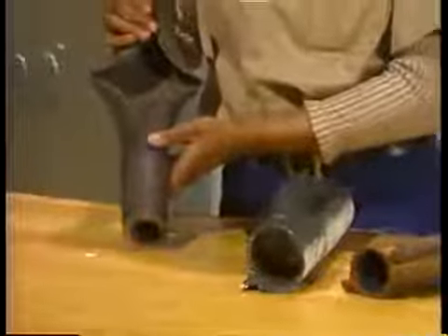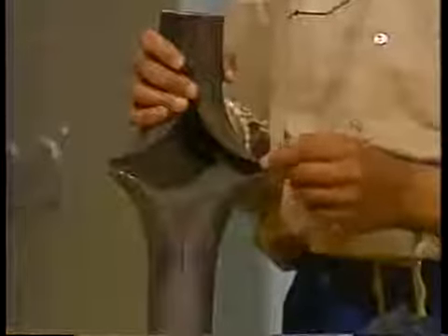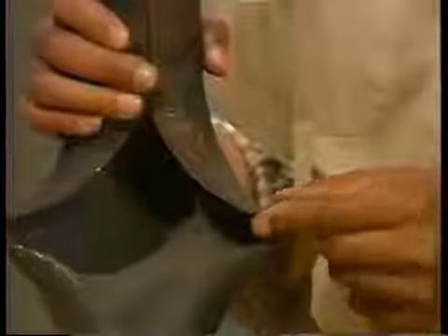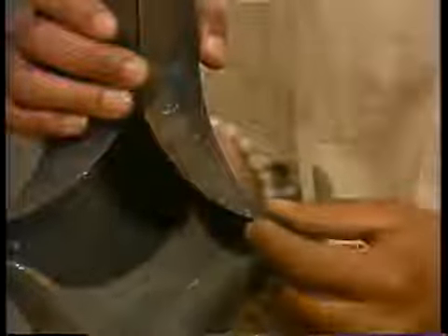Now, thick-lipped ruptures are caused by milder but more prolonged overheating. This kind of overheating is often caused by deposits on the inside of the tube. Thick-lipped ruptures resemble thin-lipped ruptures, except that their edges are thicker and more ragged, as you can see here. This kind of rupture is common to superheater tubes.